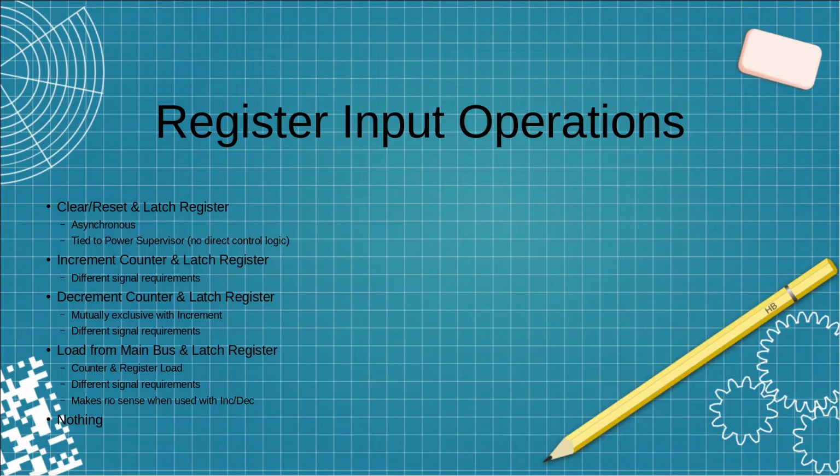So is that mutually exclusive? Technically, no. Not from a hardware compatibility perspective or a hardware protection perspective, but it's not something that we want to allow because it makes no real sense. And finally, there's an input operation called do nothing. We need to take that into account and understand that it's something that we need to plan for, and have some method of sending or not sending signals to a register or a module when nothing is to be done. We need to be able to handle that in the control logic in some way, shape, or form.